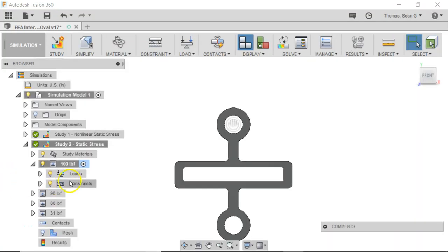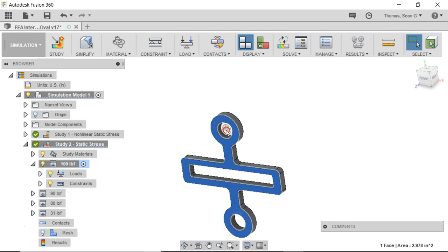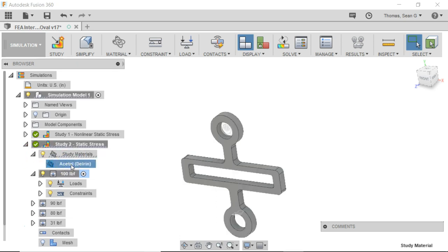In this example, we'll start out with the linear static structural simulation. First we have just this simple part where I am fixing this cylinder on the bottom and I'm pulling upward with a 100-pound bearing load. The material this part is made from is Delrin. In this case it really looks only at the elastic modulus of the material to develop my stress-strain relationship. So what you're going to see is stresses that are much higher than could physically be in this part because Delrin yields at around 10,000 psi.